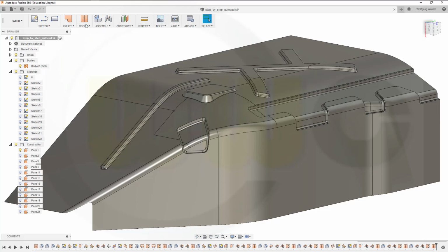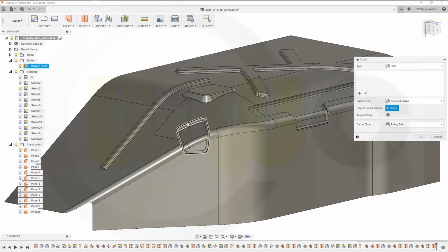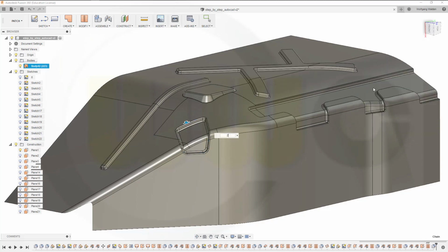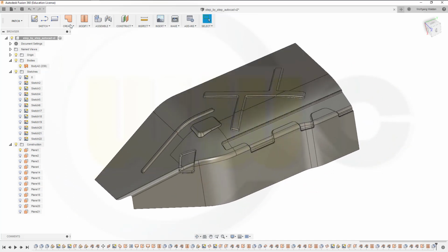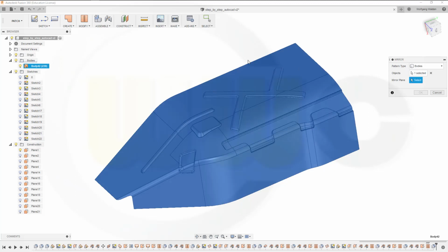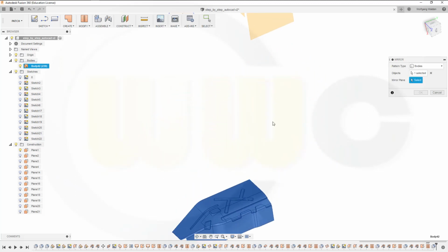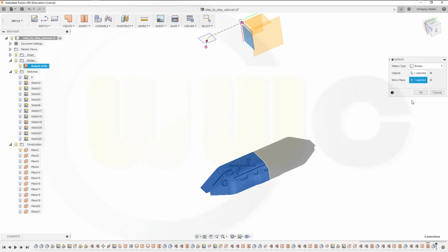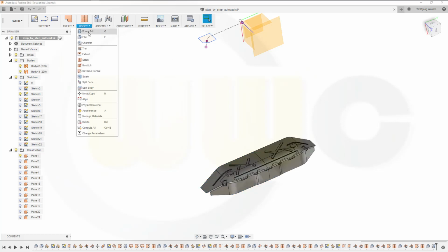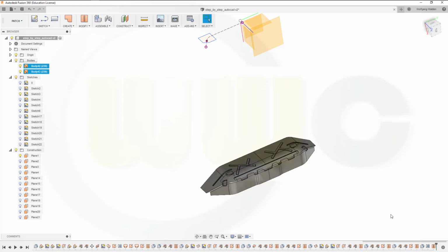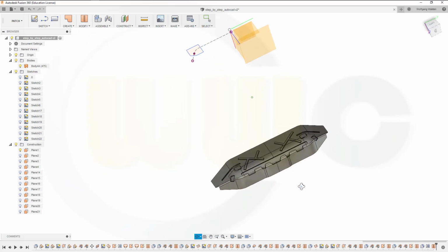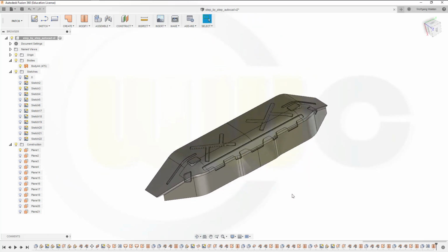Nope. Fillet on that edge and make it, let's try 2 millimeter, and it worked. Then mirror this, go for mirror, mirror bodies, this one, and the mirror plane would be that one. Okay, stitch it, and okay, I will leave the rest as usual up to you.